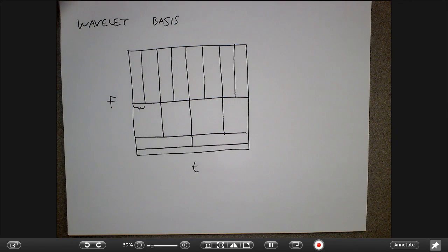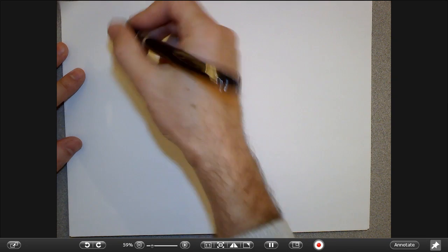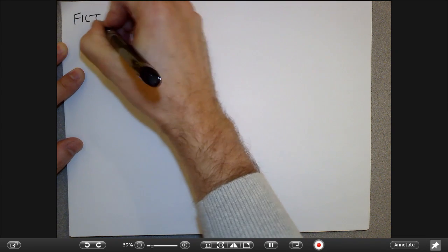So now we're going to put this on the back burner for a few minutes and talk about a concept that turns out to be related, which is filter banks. Okay, we didn't really talk about that at all in this class so far, but those happen a lot. Actually, we started to touch on it in the very last part of the last lecture on vocoders, right, where we were talking about how to make this robotic voice. What I would do is pass it through a set of bandpass filters, all of which pass stuff at different frequencies, right? And so the way that I would analyze and talk about such a system is with a filter bank.